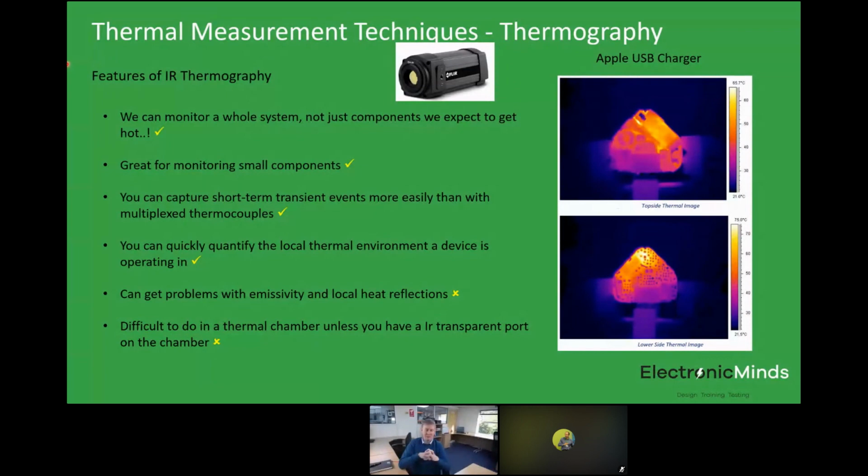Normally what you would do in any sort of magnetics like this is you wouldn't really gap the outer legs. You would just gap the inner leg, or use a distributed gap in the inner leg, and then the outer legs don't have any gaps, and you can just use normal metal cooling all the way down them.